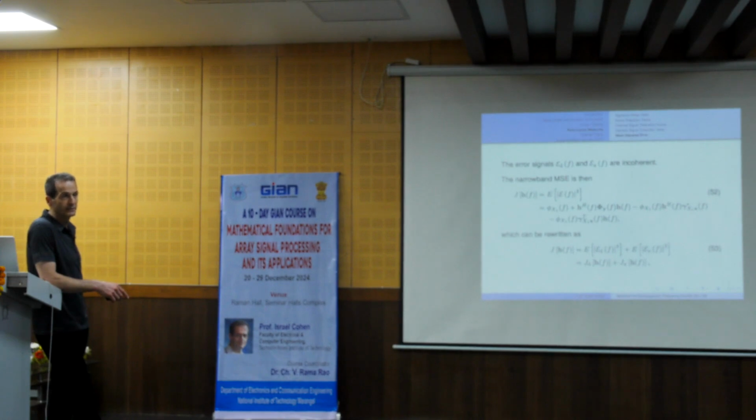What was there? ML, okay? And even we worked with matrices, so the filtering matrix was L by ML if we try to estimate L samples at a time. But even if we try to estimate a single sample of the time domain signal at a time, we have a very long filter of length ML.